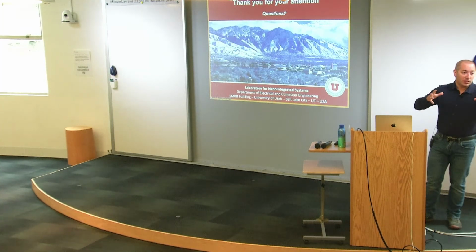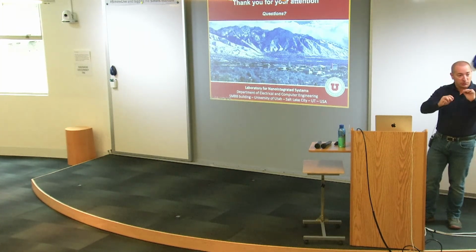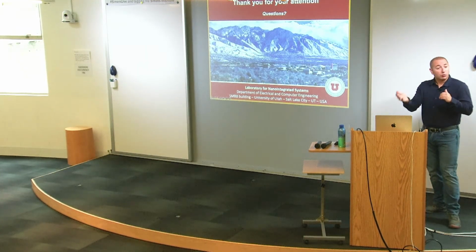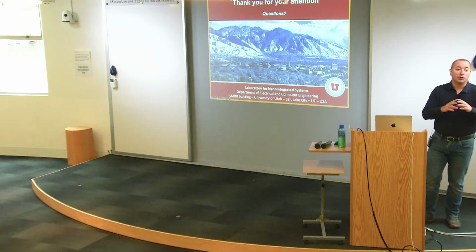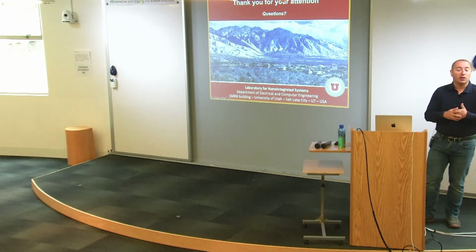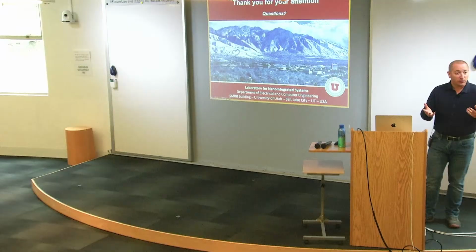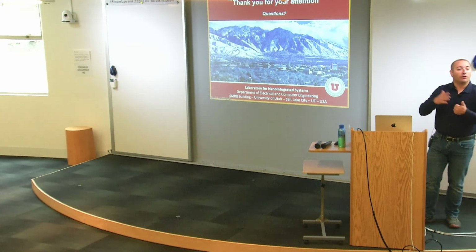Depending on the logic that you're implementing, you might have nets that do switch more than others, right? That can switch every single time if you put XORs versus NANDs or stuff like that. That will be linked to power, essentially. So you want to be able to extract from your graph representation these high-level metrics. Number of nodes will be a decent proxy for the number of gates.